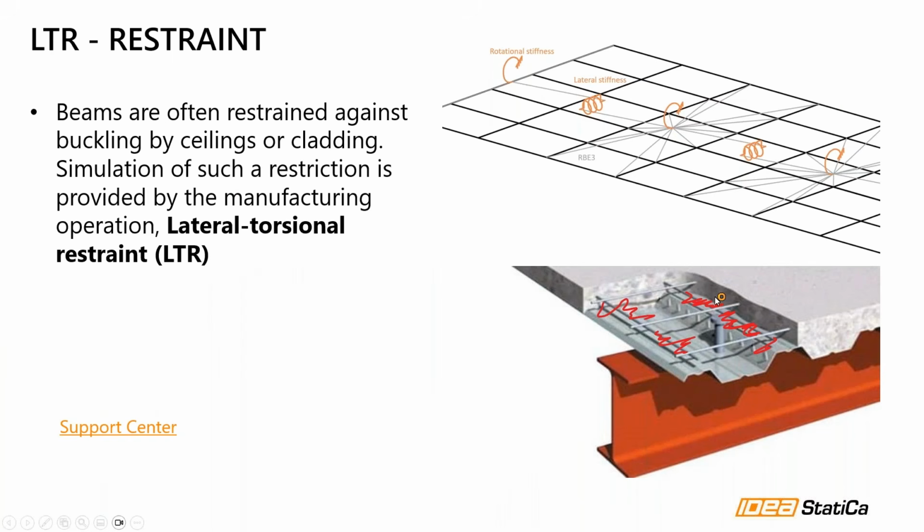But there is some continuity because there are some rebars that have some bond. If you just keep the reinforcement in this direction, coupled normal forces will be created. One is tension in the deck, and the second one is going as a compression normal force into the beam. These effects are basically neglected if you leave out the continuity of the reinforcement rebars. This effect will be dismissed. So you need to be very careful during the design of the composite deck, and if you would like to do it using the Checkbot.